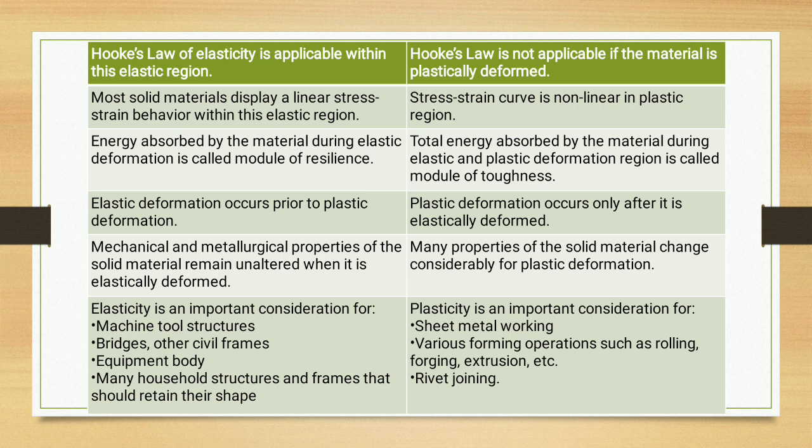In elasticity, the energy absorbed by the material during the elastic deformation is called the modulus of resilience. Whereas in the case of plasticity, the total energy absorbed by the material during the elastic and plastic deformation region is called modulus of toughness. Elastic deformation occurs prior to plastic deformation, and plastic deformation occurs only after the material is elastically deformed.